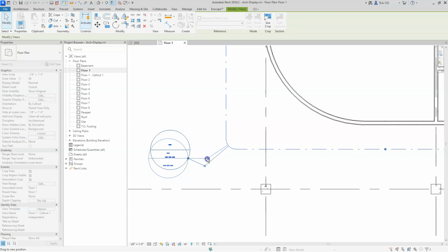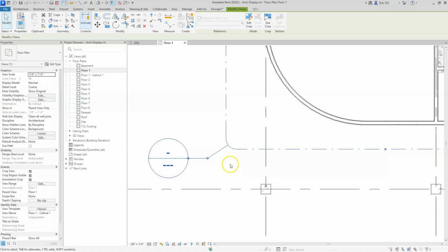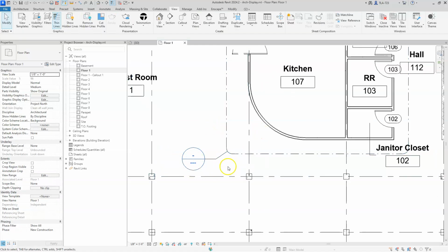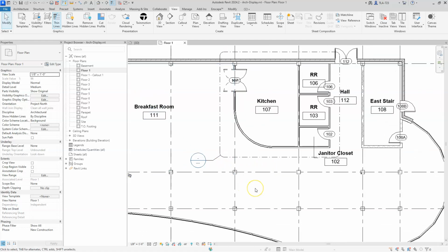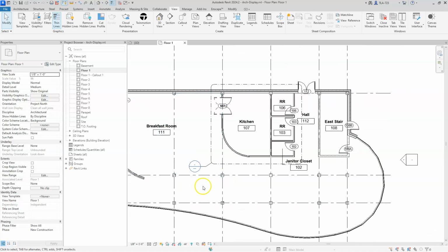Why Revit does that, why you have to do that double grab thing on this grip, I don't know, but it is what it is. But this is usually the style that we see with these enlarged view callouts. The tail of this thing comes off horizontally, and then it comes up into an angle into one of the corners. It's not always done that way, but most of the time that's what we see. So it's a good idea to take a minute and practice that, just make sure that you have a little bit of an understanding of how those grips work on those callouts.